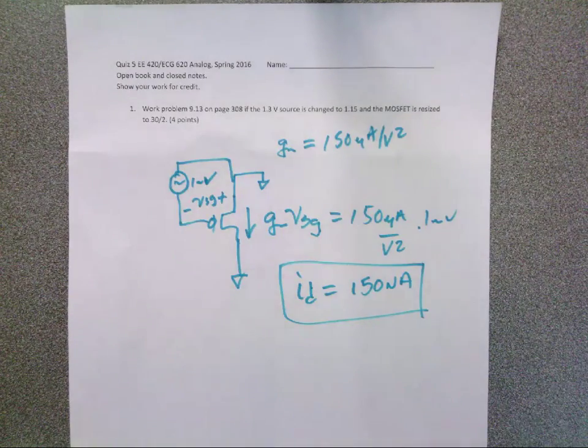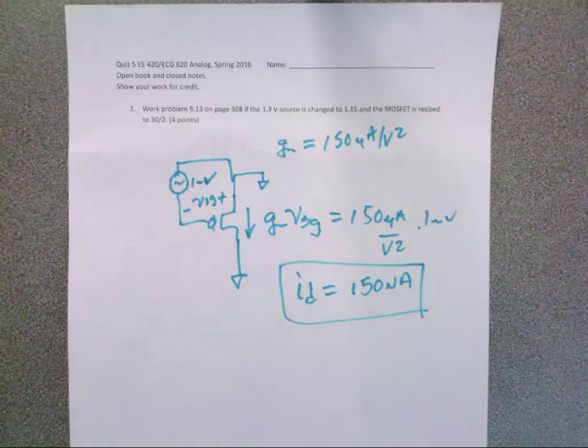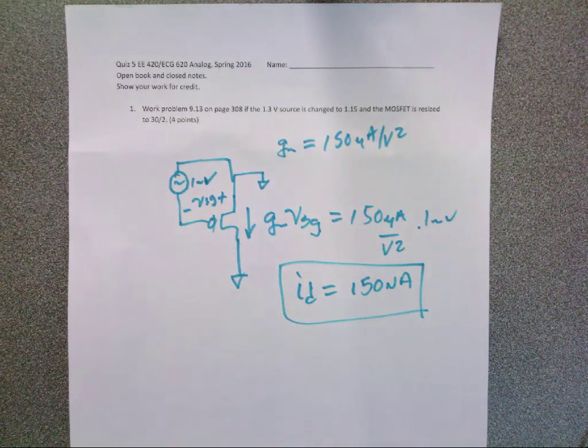You know what we talked about earlier, when you're doing a DC analysis on an NMOS, let's say you just want to test for VDS. Can you just do VDS equals current times the R channel, if the NMOS is in triode?